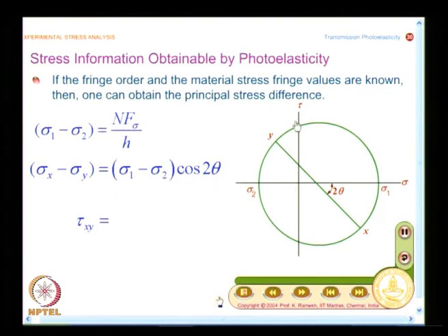You all know the Mohr circle, you draw it in the sigma and tau plane. I draw a circle and each point denotes a plane, and here it is the x plane and this is the y plane, and in Mohr circle all these angles are twice the actual angles, that is why planes at 90 degrees are shown at 180 degrees. And when I have so many points on the boundary, it shows all the possible infinite planes.